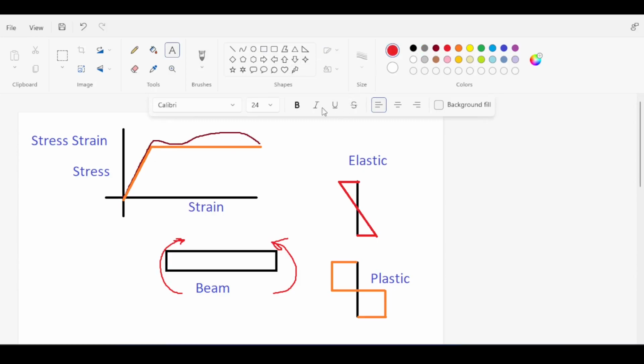Now the first thing I want to talk about is the stress strain diagram. Once again, you need to check out your mechanics of materials courses if you want to get a deeper understanding of this. But the bottom line is, strain and stress behave linearly in something called the elastic range and nonlinearly in something called the plastic range. The actual stress strain curve is different, but we usually, as civil engineers and even researchers, have our own simplification, which could be a simple bilinear relationship or any other relationship of your liking. Of course, the relationship depends on the code.